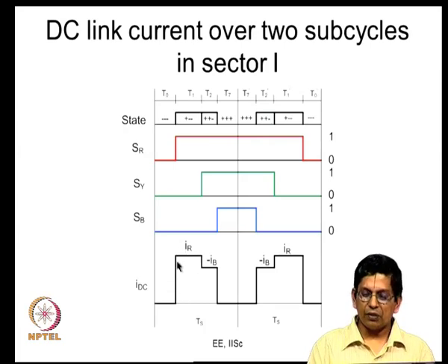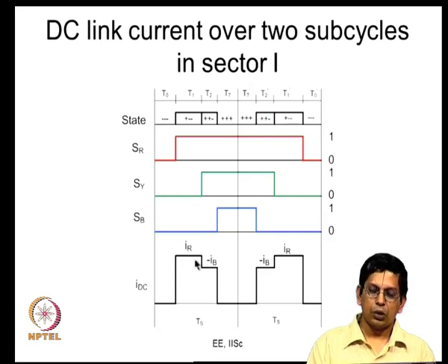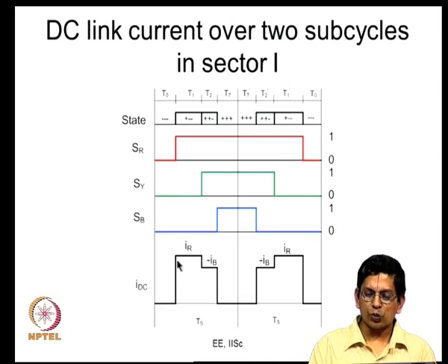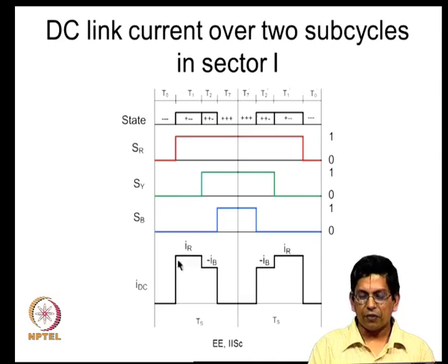You can see that we are looking over a short interval, and therefore, as I mentioned already, in IR we have ignored the harmonic component. We are considering only the fundamental component, which sometimes we would call IR1. The fundamental component is a sinusoid. We are viewing it over a small interval of time, so that looks like a flat line. So, this is your IR.